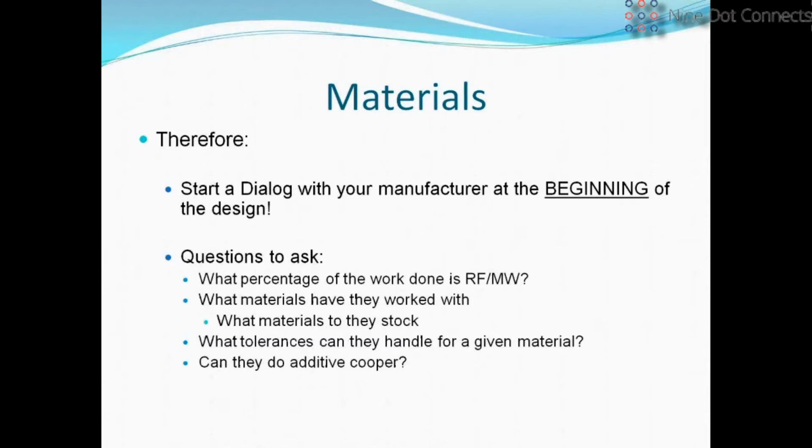Number one, what percentage of their work is done in RF and microwave? If they're saying, yeah, we've done 1 or 2 before, and 98% or 100% of their work has pretty much been in traditional rigid PCBs with FR4, that's probably not the best company to go with. You don't want to be their guinea pig. Again, it's about risk mitigation. Also, the materials that they work with, and in particular, what materials are they stocking?